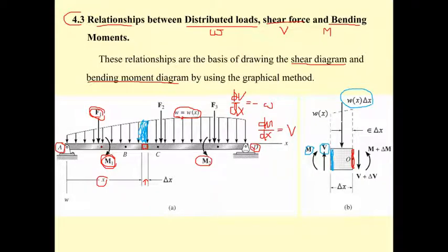And in the opposite way, if the moment is counterclockwise, the counterclockwise moment will produce a decrease in the moment on the moment diagram at that point.